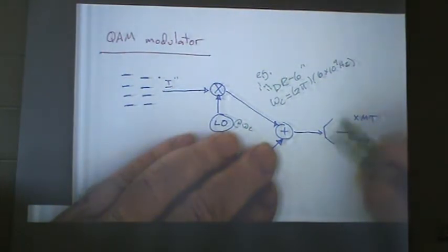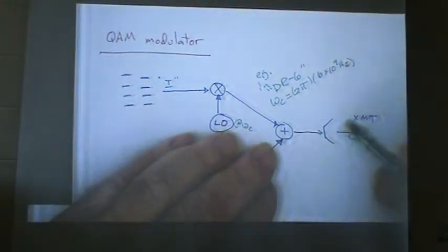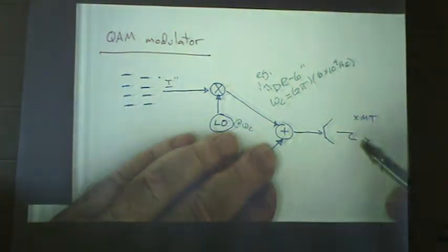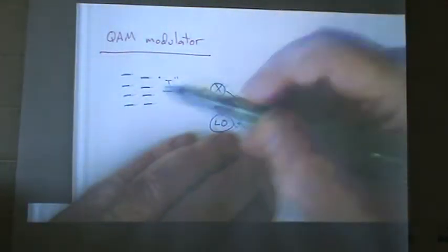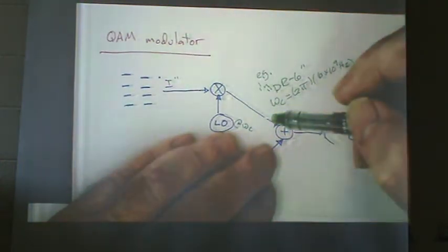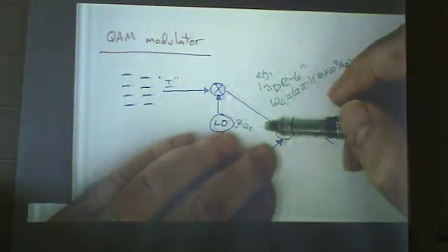This symbol represents the transmitter. Think of it as kind of like an antenna. Now at optical, it doesn't have to be an antenna. This is now a fiber. But I take your phone calls and I bring them up to some carrier frequency, the one corresponding to 1550 nanometers, if that's the color I'm at.